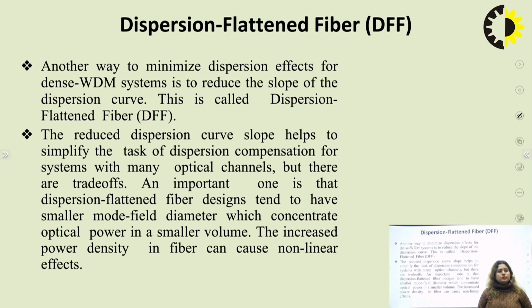So the reduced dispersion curve slope helps to simplify the task of dispersion compensation for these systems with many optical channels. But there are trade-offs. An important one is that dispersion flattened fiber designs tend to have a smaller mode field diameter (MFD), which concentrates optical power in a smaller volume. So the increased power density in the fiber can cause non-linear effects here.